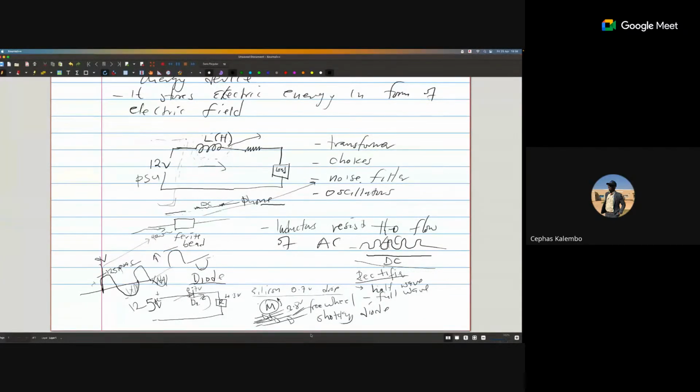So if the available voltage that you have is 4 volts, putting a diode in between to drop that 4 volts to 3.3 volts is a perfect solution. However, it is not a precise voltage regulator, because the voltage drop is not perfectly constant and varies slightly with current and temperature. If your temperature varies, the voltage will vary. If the current varies, your voltage will vary.